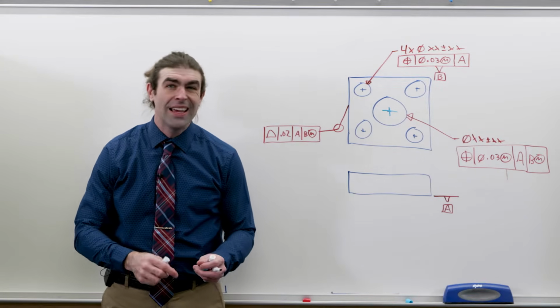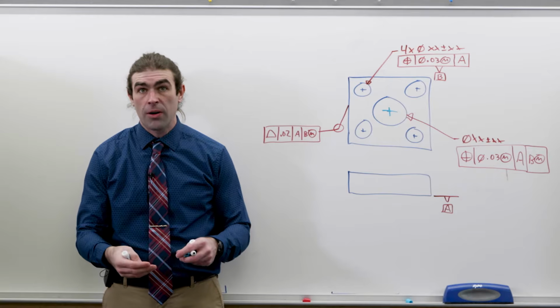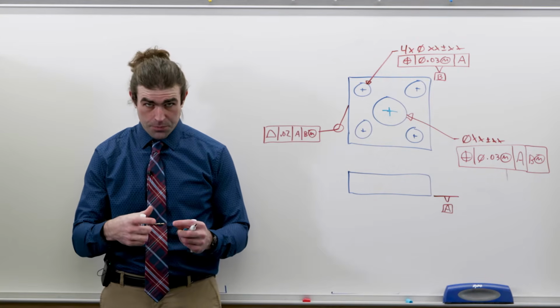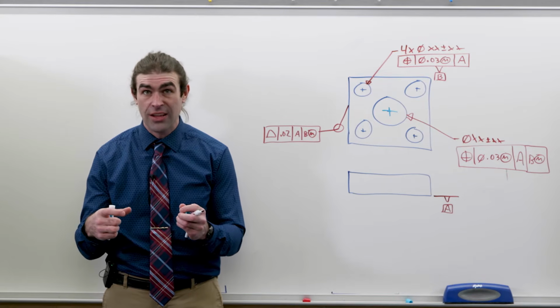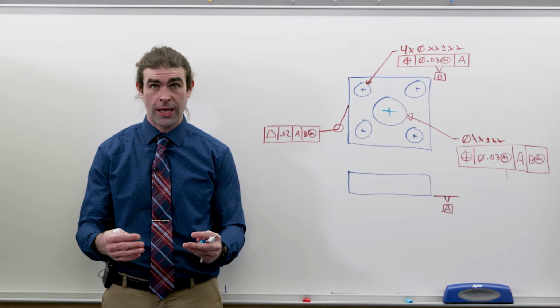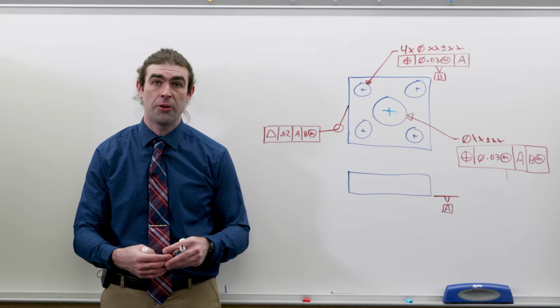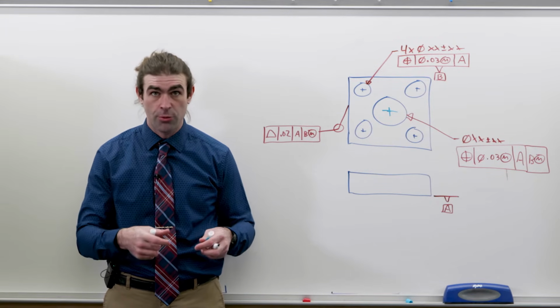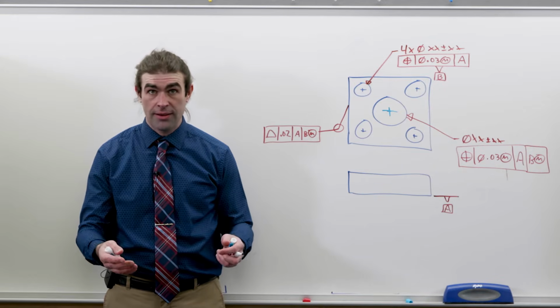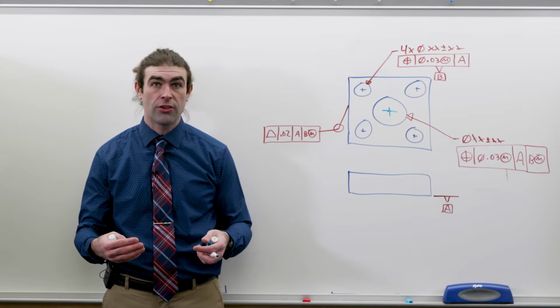pattern of holes. If you called that out at RMB or RFS, you would have to have 4 pins that expand at the exact same time, that are perfectly located, so at least gauge maker's tolerances. They all expand to capture the part until it stops wiggling. That can be done, and they do make fixtures and gauges for that.